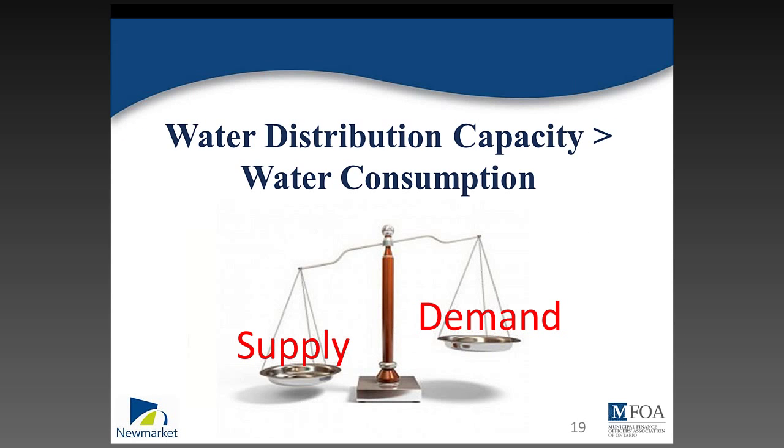One idea of why our non-revenue water is rising is because while our demand for water is decreasing, we are expanding our capacity to deliver water. I have this image here to illustrate that the water supply is exceeding demand. When supply exceeds demand, water slows down in the pipes and the water begins to age in it. When the water gets old, it becomes a risk to human health. To ensure that our water stays young and safe, we have to flush the water from our system to maintain the quality more than we otherwise would.